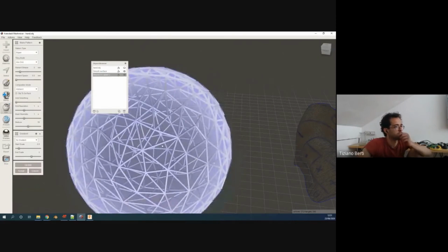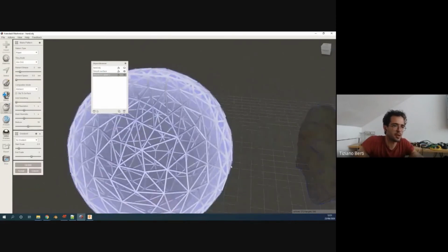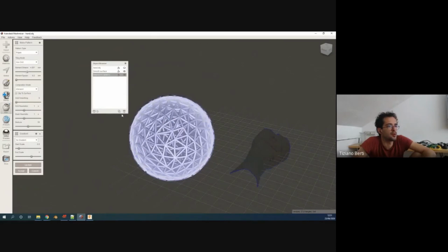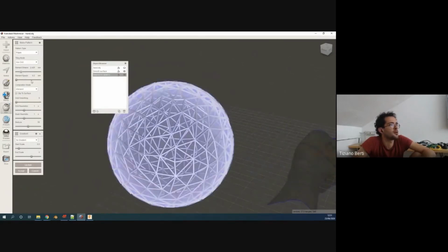So we were talking about this tool. If I want to make something like this on my brace, I just use this tool. I just need to be careful about the dimension of this piece in order to be 3D printable. So on an FDM machine, we just need to, I think, use 3mm, 4mm around that in order to be printable.